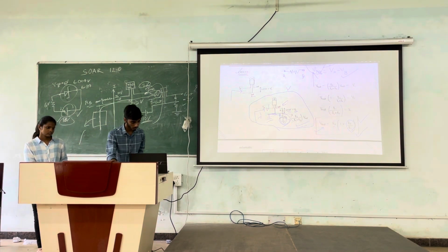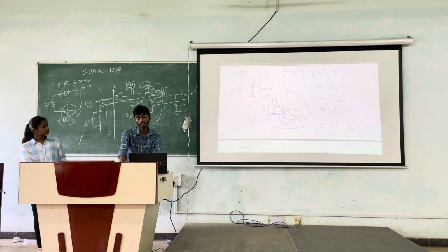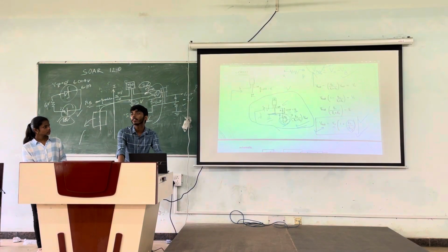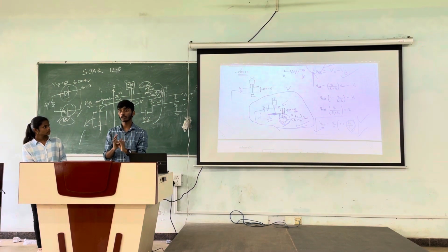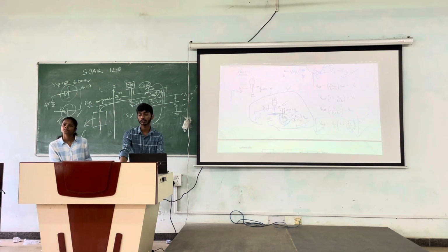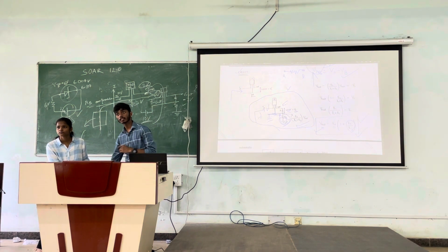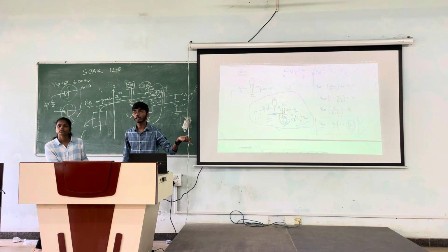Like if we have any junction, if we are having this port, we are saying this is V out. But with respect to what? With respect to ground. We are considering ground at 0 volt. That's not actually at 0 volt. We only say that this is a reference point. Okay, we always define potential difference. We don't say that this ground is at 0 volt. We just assume that if it is 0 volt, then with respect to this, everything is at another voltage. Okay.